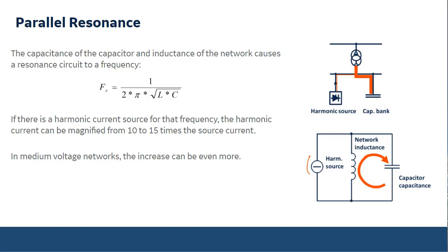Now when you have the connection of the system so that you will have now resonant frequency same as some harmonic in your network, this resonance between the transformer windings and the capacitor will amplify this harmonic quite a bit. So this is why we need something else than this tuned filter network.